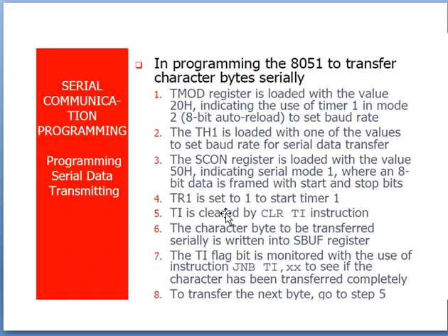Then the execution of this timer is controlled through the TI flag. TI is continuously observing how much value is getting updated in your TH1 register. Once it reaches the maximum value, then TI is going to go high. Then it has to be cleared so that it can take you to further timer operations. At the initial stage TI has to be cleared, so that once it reaches the maximum value, only then it is made high. So automatically TI is going to update to 1, right?